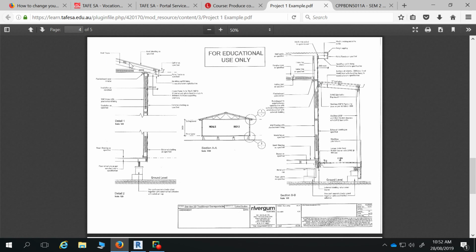They haven't got that done here very well. They've done it for this one, this one, this one, and this one, and this one, but they've actually missed 2 or 3 of them are justified left, so it's a bit uneven. So it's just a matter of going through drawing and saying, right, now I just want to re-justify those so that they all sit in closest to the arrow. That makes sense? So you can see on this detail they've actually done it nicely. But this one it's just a bit messier.